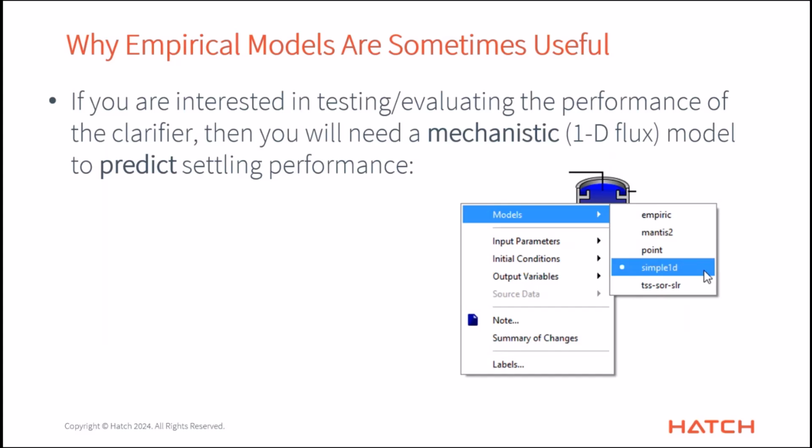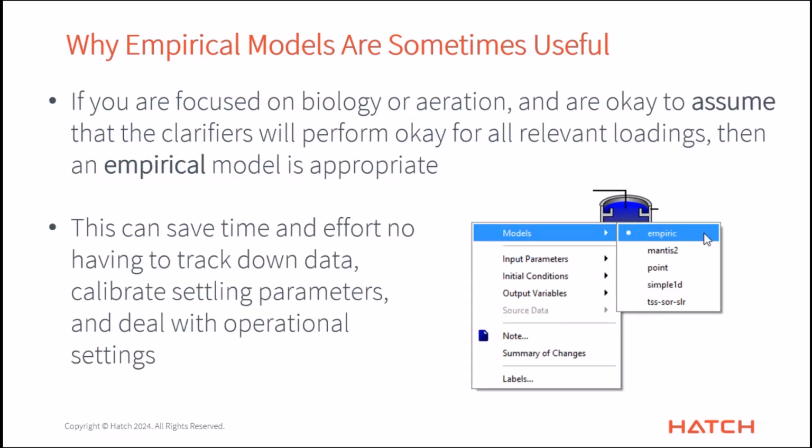Right. Okay. So as I mentioned, if you're interested specifically in what's happening in the clarifier, and you really want a prediction of performance, I want to see, for certain loading and operation, what is my effluent TSS, you can use the mechanistic model. I guess I'm just re-emphasizing here that if you're fine with assuming that they're going to have good performance or a given performance, you can set that directly, say I'm removing 99% of the solids and move onwards.